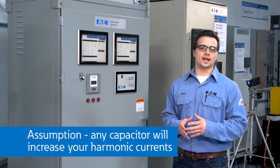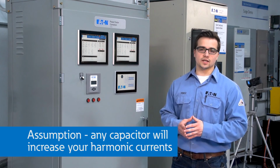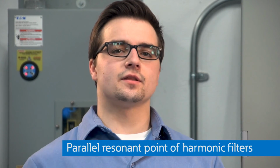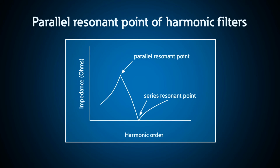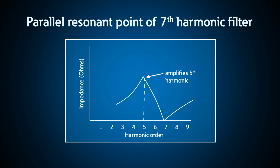You can assume that any capacitor will always increase your harmonic current on the system. The question is, how close are you to resonance and how much will harmonic currents increase? Another important thing to consider is the parallel resonant point of harmonic filters, which in general is 1 or 2 harmonic orders less than the tuning point. So for a 5th harmonic filter, that would be around the 3rd or 4th, where very little harmonic current exists. But for a 7th harmonic filter, the parallel resonant point is just above the 5th harmonic.